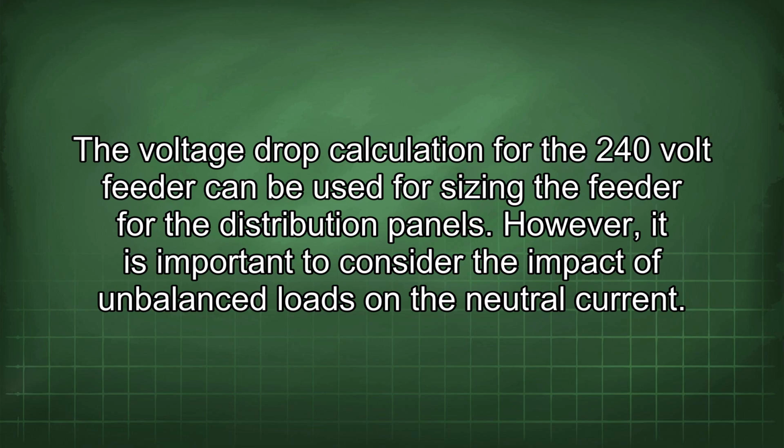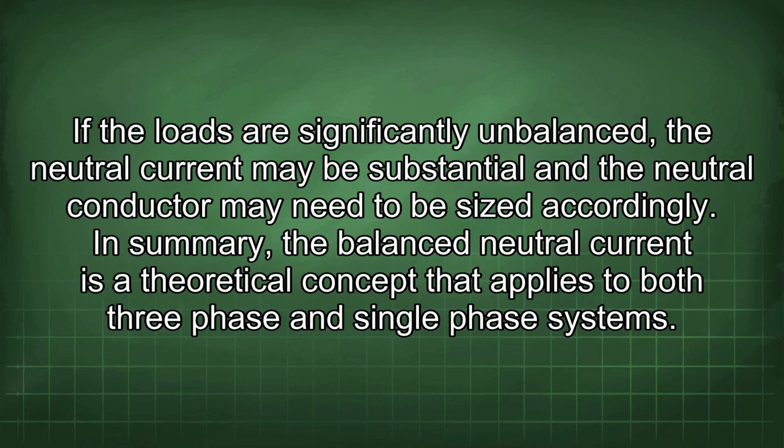The voltage drop calculation for the 240-volt feeder can be used for sizing the feeder for the distribution panels. However, it is important to consider the impact of unbalanced loads on the neutral current. If the loads are significantly unbalanced, the neutral current may be substantial and the neutral conductor may need to be sized accordingly. In summary, the balanced neutral current is a theoretical concept that applies to both three-phase and single-phase systems.